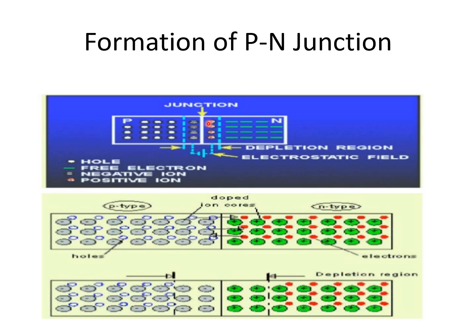Negative ions, positive ions. Whenever p-type and n-type materials are attached, we know that opposite charge carriers are attracted. So see here, the holes at the junction will be attracted towards the electrons in the n-type and combine. At the same time, the electrons in the n-type will be attracted towards the holes in the p-type, because holes have positive charge, electrons have negative charge.